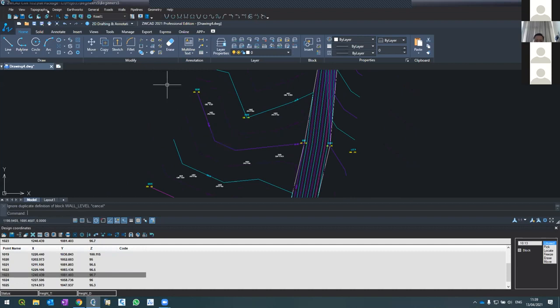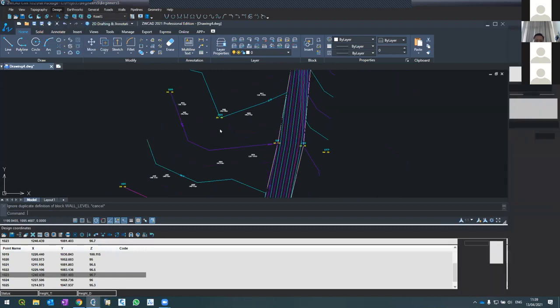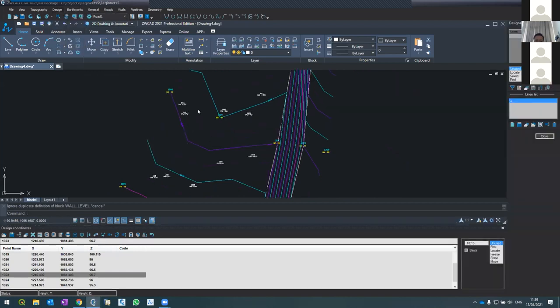And to be on the safe side, like I did in the topography, I'm doing topography lines, and I will create a break line in the bottom, and on the top I don't need it, it's the outside. So I go here, this is the bottom of my pit. This is the bottom of my pit.